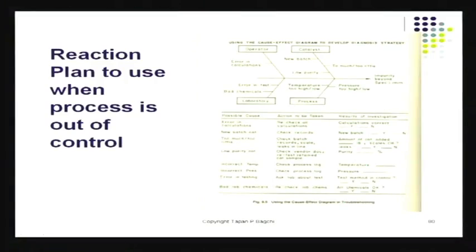Now say you have found a point beyond control limits. Stop the process. Pull out your checklist, and your checklist is this. This is your checklist. And very systematically go over the items, and I've listed them out here. So you notice the factors here, the causes that might have caused, in this case, impurity to go beyond specification limits. Impurities must stay within some specification limits.